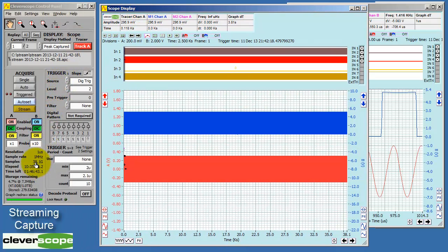Here we can see the real detail. Sample rate 1 MHz, 38.1 gigasamples, and 10 hours of capture. Streaming is a way of capturing very long-term information at high rate and then interrogating it using the spectrum display, maths, the tracking graph, signal information, and transfer to MATLAB for useful information that is almost impossible to find any other way.